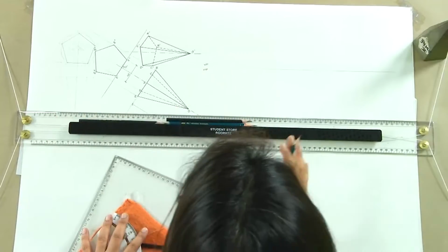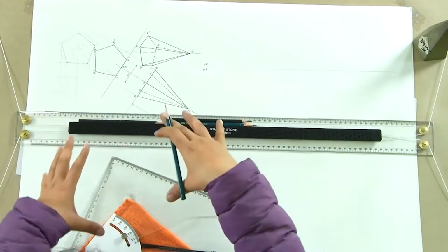So, let us assume that we have a cube to start with, and this cube is inclined at 45 degrees to HP and it is parallel to VP, the axis of the cube. And say the size of the cube you can assume to be a 7 centimeter cube. So, to begin with, the cube is placed in HP and it rests in HP on one of its edges finally. So, let us draw the 7 centimeter cube in its original position.